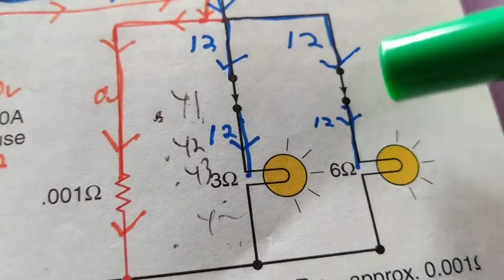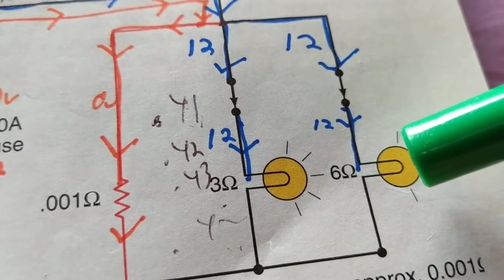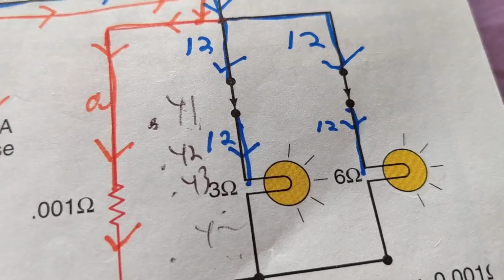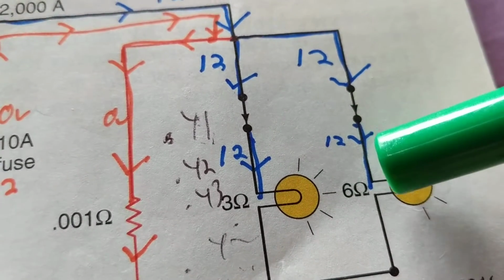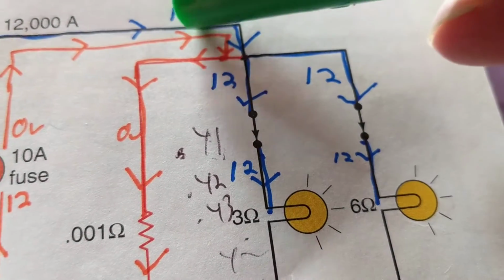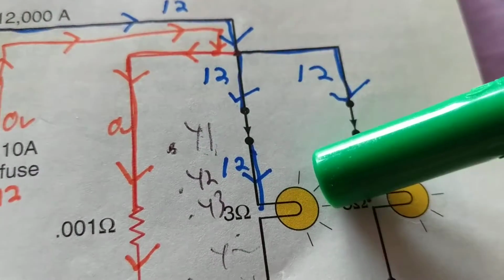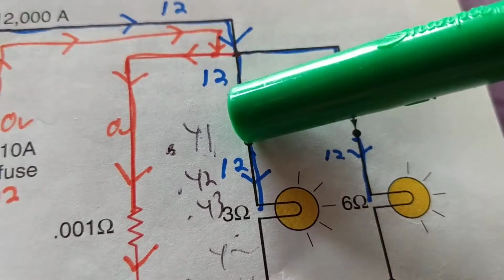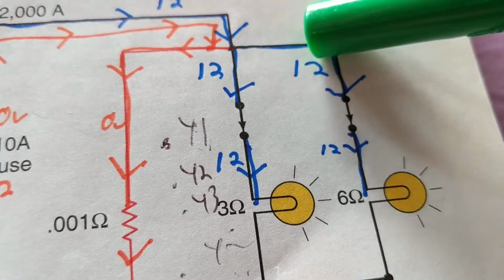Let's say this is lit and this is extinguished. You change the bulb. You said, oh, that's easy. Easy fix. That's the bulb, right? You change the bulb, same thing. Where's the open? Is it over here again? Nope. Why not? Because both will be off. This is a common to both, see? Where would be the open? Anywhere from here to here.